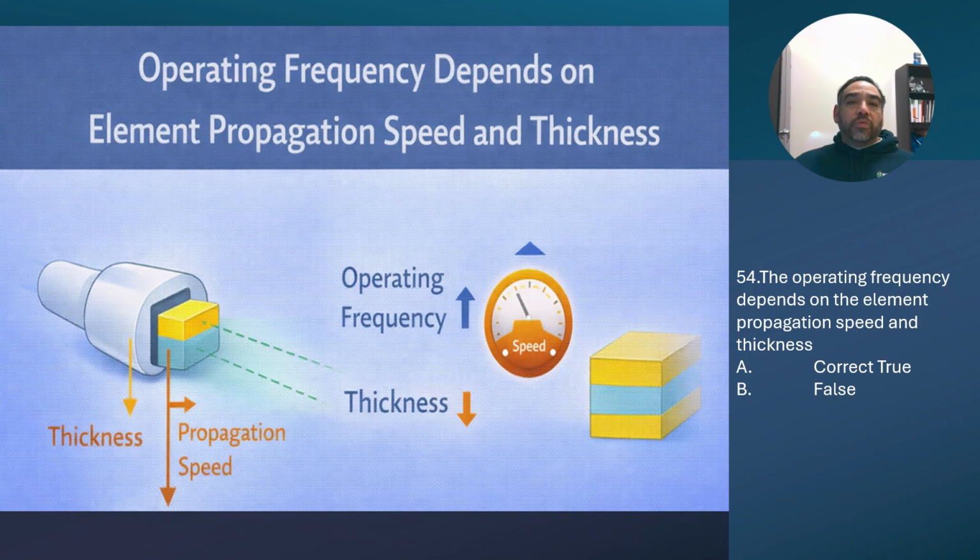So what this means physically, and again, if any of you design transducers, please leave a comment. The crystal vibrates most efficiently when its thickness equals about 1/2 the wavelength inside the crystal. That kind of sounds familiar. It kind of sounds similar to something called the Nyquist theorem, but I won't move into that. They're not related, but I'm just saying it does sound interesting.